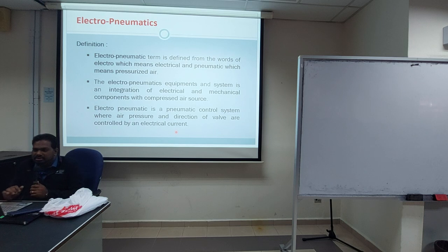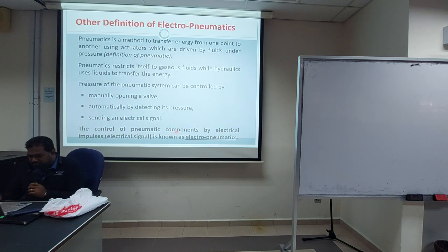Usually in a pneumatic circuit we have pilot operated valves, meaning you give pressurized air to control a valve. But with electro-pneumatic, instead of using pressurized air to give input to a valve, we use electrical relays. Okay, other definitions of electro-pneumatic you can see here.